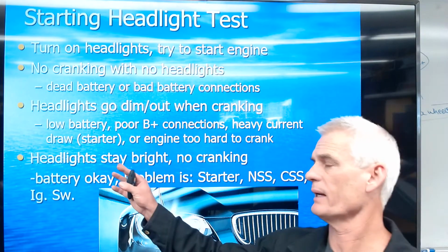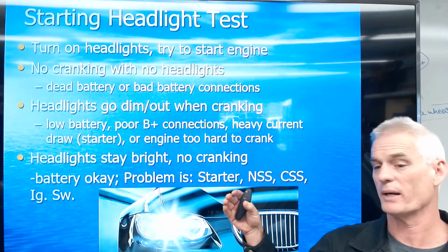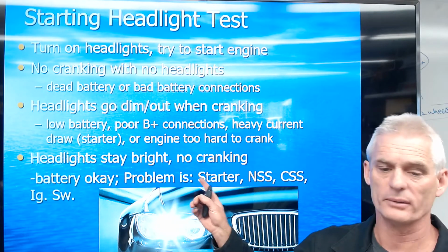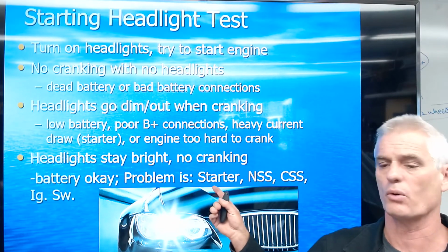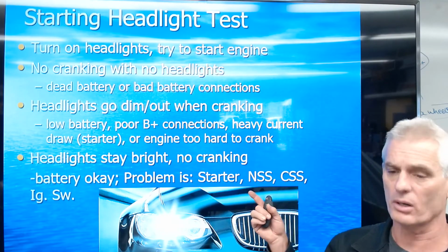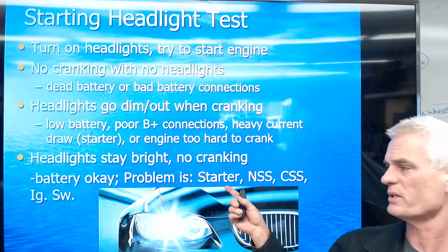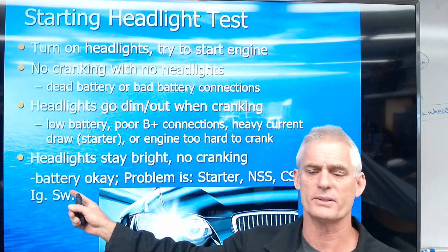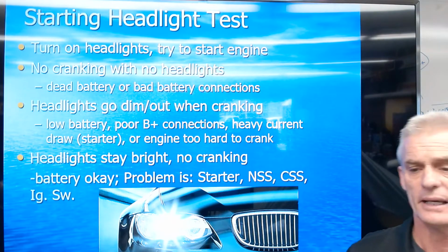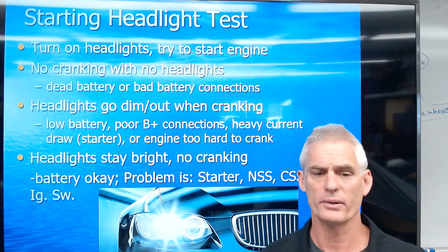But usually when the headlights stay bright and there's no cranking, which means that the starter's not even trying to pull power, or it's not able to pull power, it's something in the control of the starter. When I say control, these two would be in the control, the alarm would be in the control, the computer would be in the control. It could be in the starter itself, but we're not thinking battery. Is it smart for us to do a quick look at the battery and make sure cables are clean and it's full of charge? Yes, it's important that we should do that.